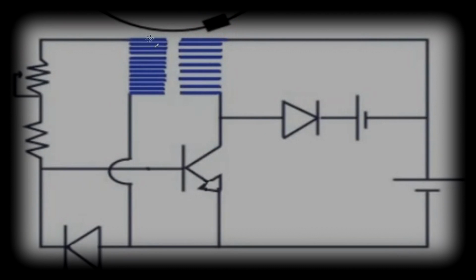When it saturates this trigger coil, it will send a positive signal to the base, and the negative side will hit the emitter, triggering the transistor. You close the gate right here. So there's no conductivity from here to here until the transistor closes the switch. And that happens when the rotor magnet falls over the trigger winding.